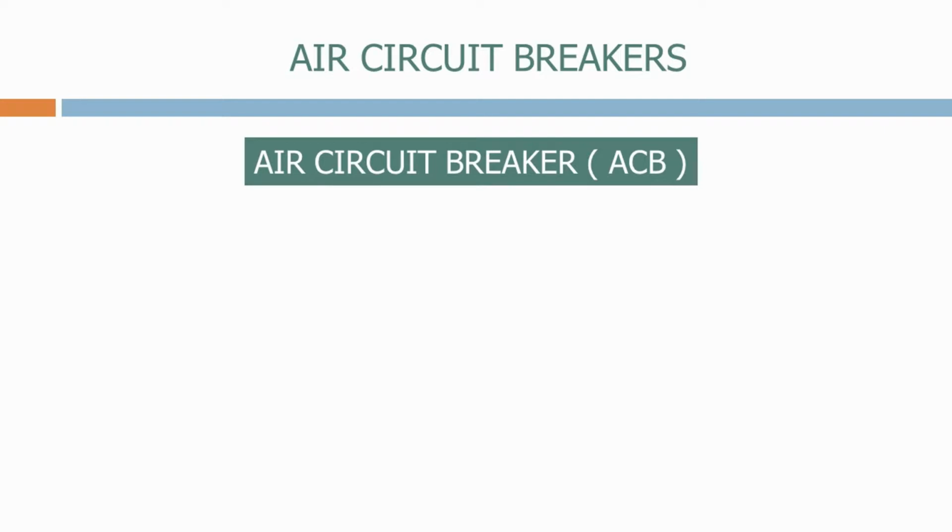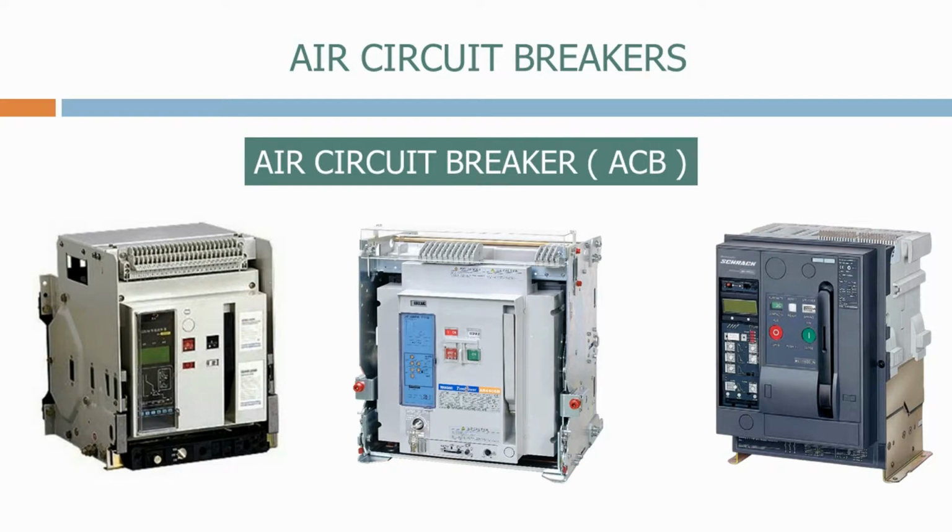Air circuit breakers, or ACBs, are used widely on the low voltage system. They are used on higher current, lower voltage industrial circuits. They are the most advanced low voltage protection device that we use, and they normally have multiple time and current curves available. They tend to be used where we need incomer circuit breakers, as they have more features and settings than miniature circuit breakers and fuses.